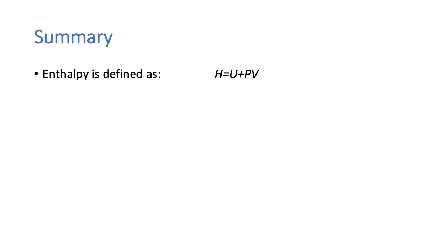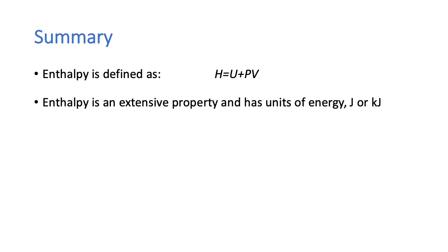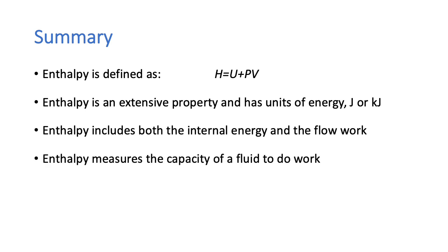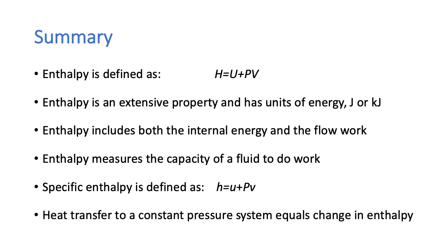To summarize, we have defined a new property enthalpy, and we have defined it as H is equal to U plus PV. Enthalpy is an extensive property and has units of energy. Enthalpy includes both the internal energy and the flow work. The enthalpy measures the capacity of a fluid to do work. We have also defined the specific enthalpy, and the heat transfer to a constant pressure system equals the change in enthalpy.